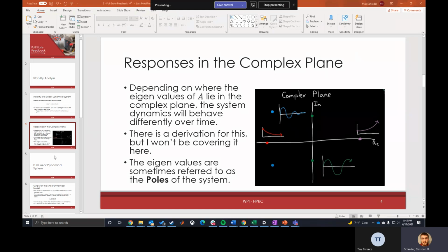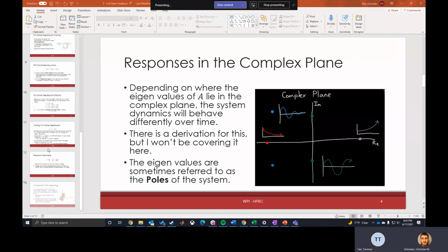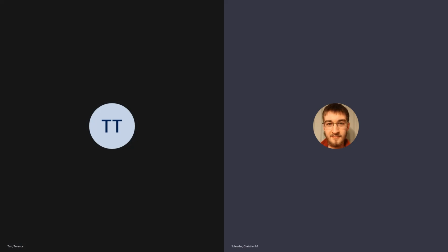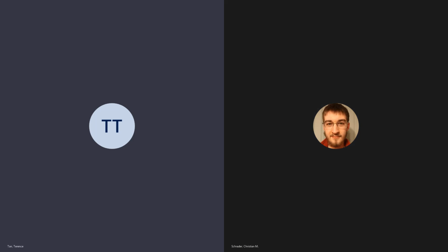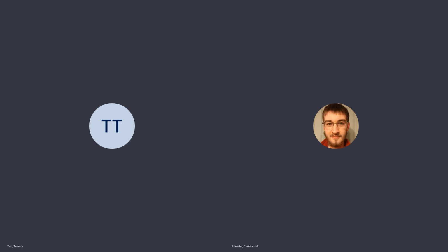The end goal of the problem is to have it be overdamped, so basically on the line. But we could do that step next. So you would have to get rid of the imaginary number to get an overdamped system. Yeah, that would mean you want a pure real number. So we'll do that next. I don't think guessing is going to work, that's going to take forever. Yeah, that's probably a bad idea.